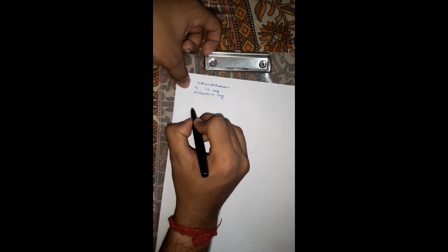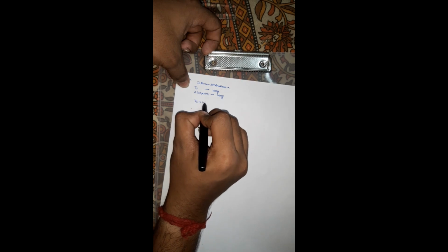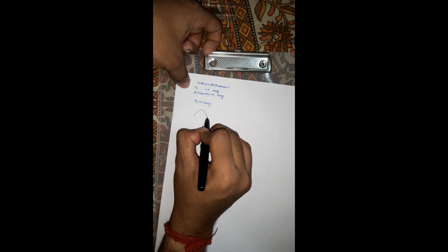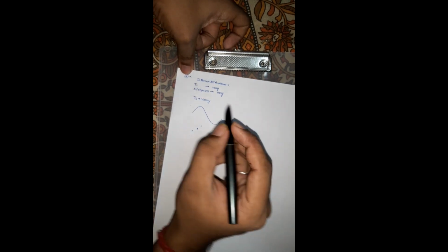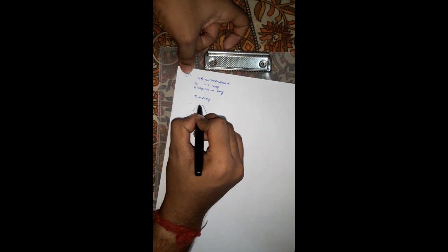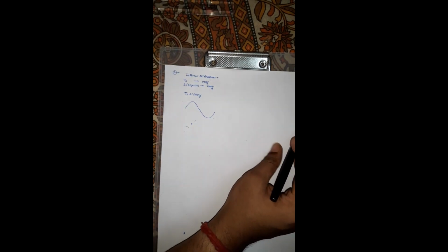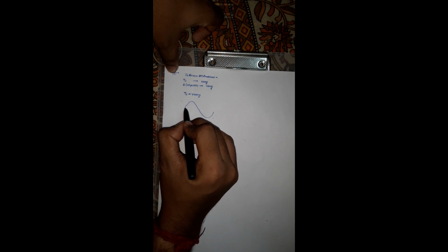If we vary the sampling time, that means according to the input signal the sampling time will be varied, but the step size will remain constant. If it is noticed that the input signal is varying too much, or the slope of the input signal is very high, then it will reduce the sampling time.